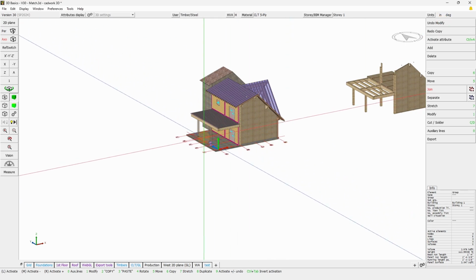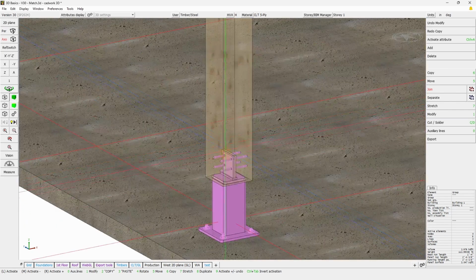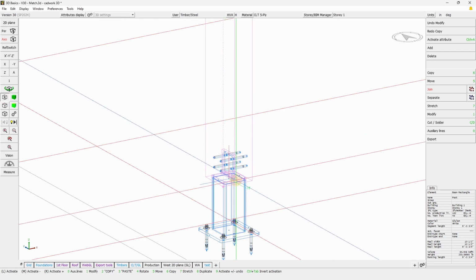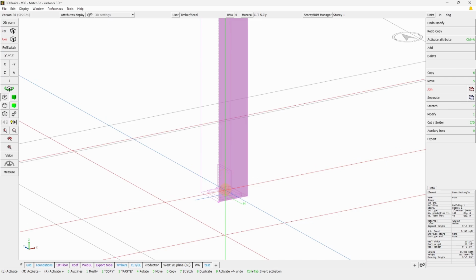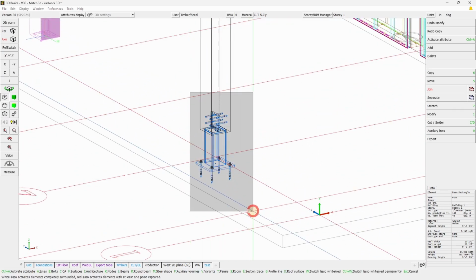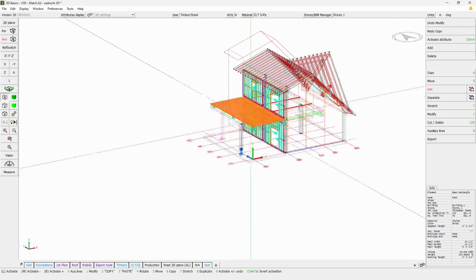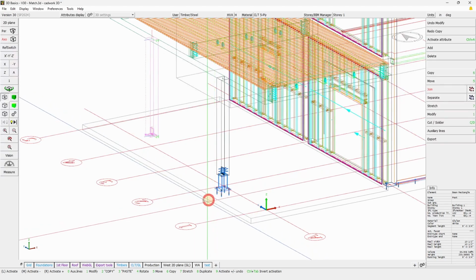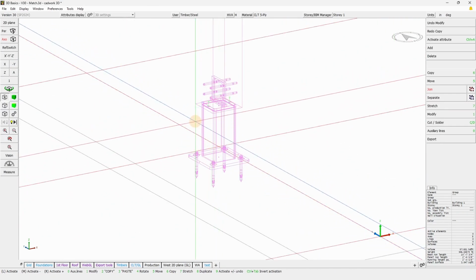This can be really useful, for example, in this example with connections, mostly because that copy reference is using the system access of your reference element and the one of your target to reorient the copy. So here, for example, if I had my post at a different elevation, at a different angle, my copy will always be placed correctly as it is placed on that element.